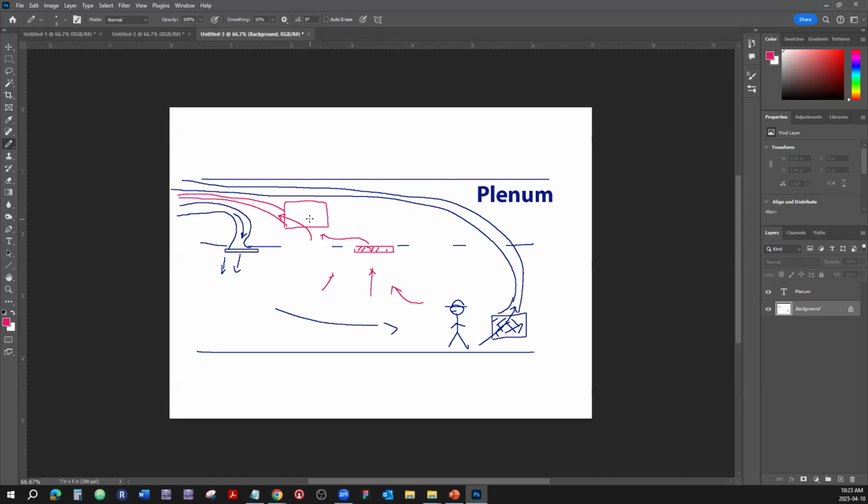That cavity or the cold air return, kind of a register, can serve more than one room. So the ceiling space could be open above the ceiling tiles. It could be open and it could be common to 3, 4, 5 rooms. And that huge intake vent is going to take all the air return into the furnace.